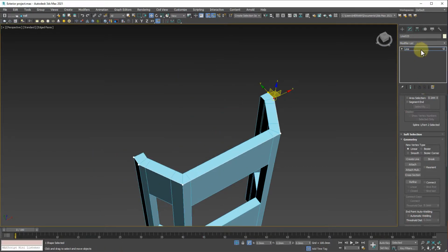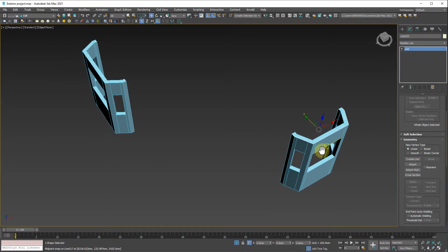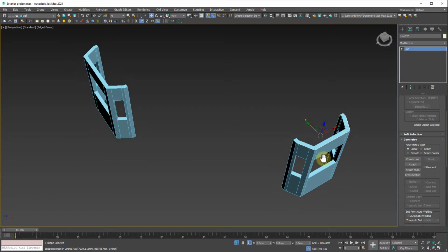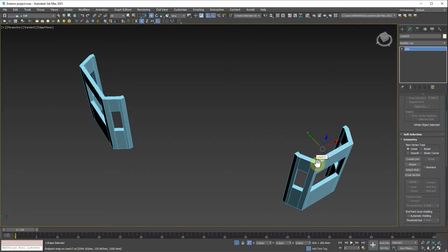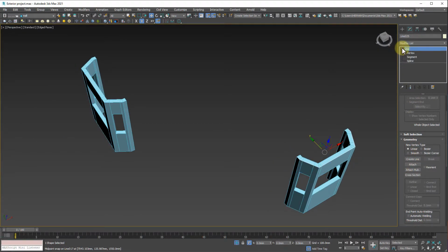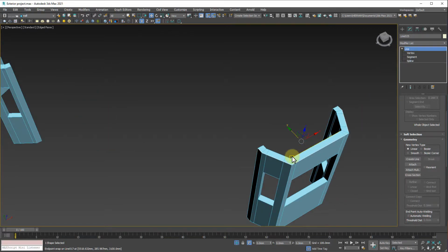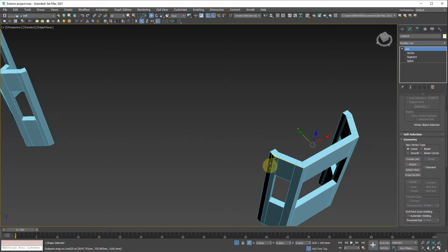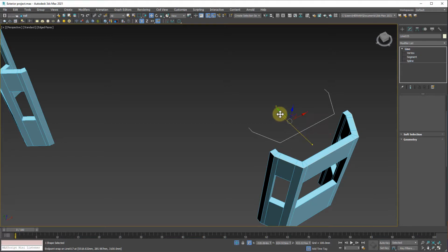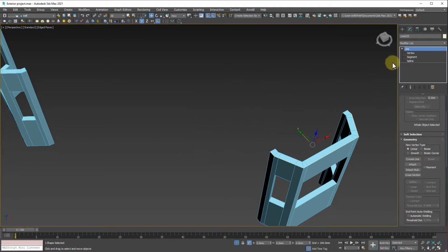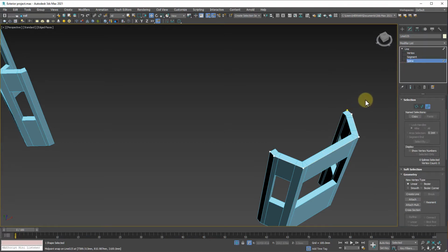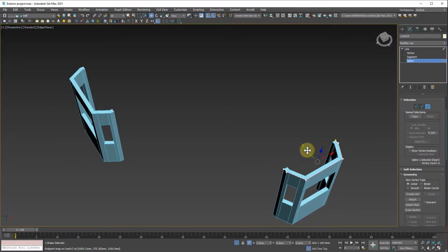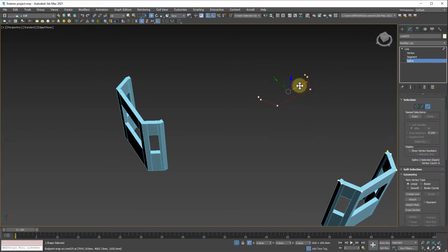Since I already terminated the shape tools, I'm going to copy the line. If you want to copy your lines, no need to use the clone method, the one where we drag and then clone. You can use your line modifier here, simply select spline, select this one, then shift and drag, so you already have the clone for the line.